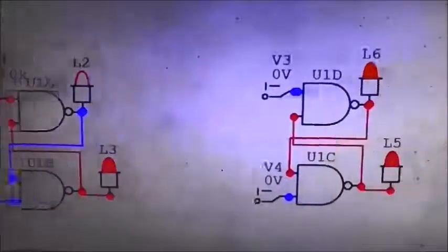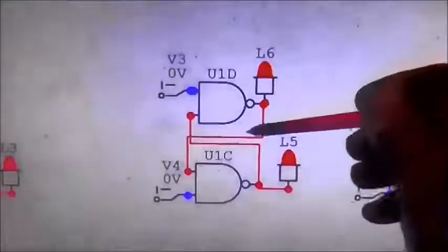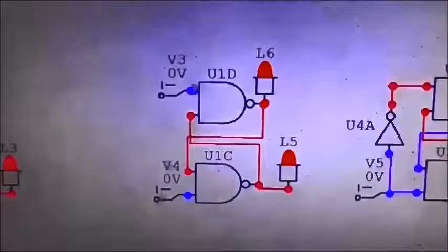If we move on a little bit more, here it is in its basic format, and you can see the feedbacks there, and you can also see the problem. Okay, so what I'd have to do is, if I kept the reset switch high and set that low, it'll switch over. If I now keep the reset switch high and set that back to high, it won't do anything.